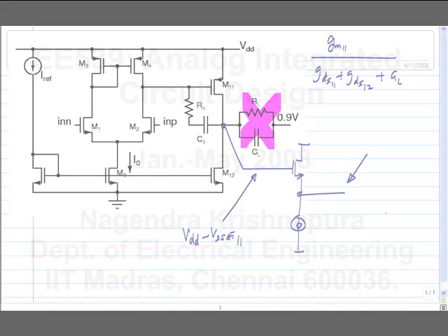This is one reason why source followers are not very popular in present day CMOS technologies, okay, where the available voltage is small. Before, if you look at traditional op-amps, or if you open up the block diagram of 741 op-amp, you will have emitter followers at the output. You will have class AB stage, which consists of a PNP and an NPN emitter followers.